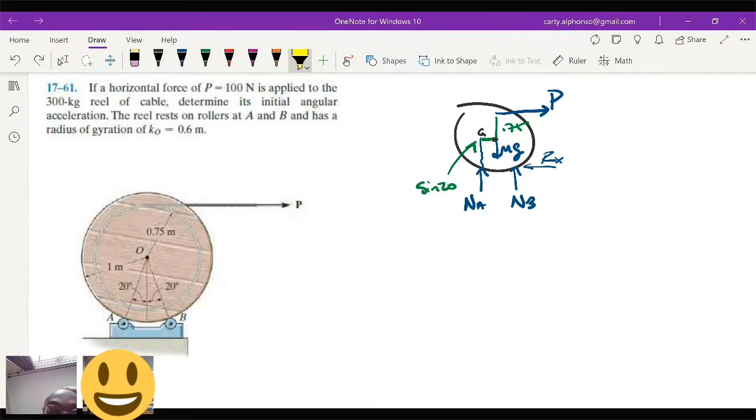All right, so we're going to put the reaction in the X direction on that guy. And it looks like it would only be on B. If you take a look at the way that A looks, it doesn't look like there'd be a reaction that would point like that. Since its weight is pushing down, you get the normal. This is pulling that way. The reaction wouldn't be generated on A. The reaction will be generated on B, because B looks like it will be the only thing to stop it from tipping over. Make some sense? Yeah. And so that's how I'm going to do that.